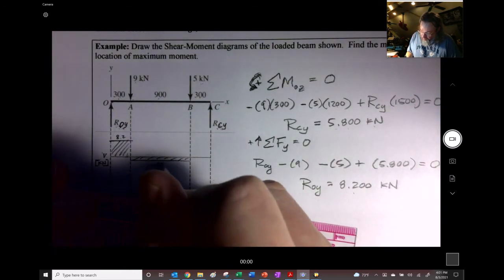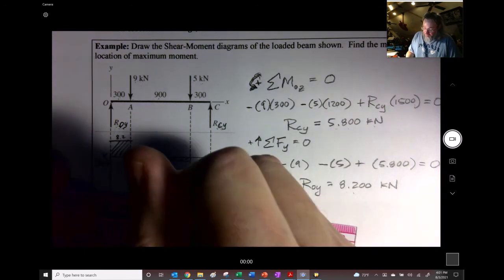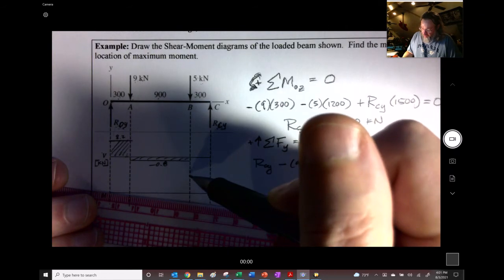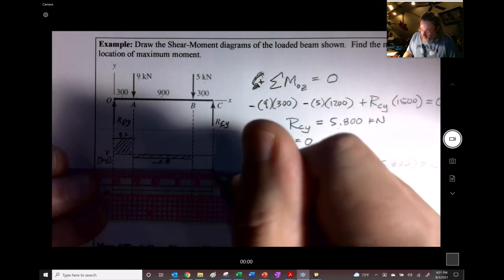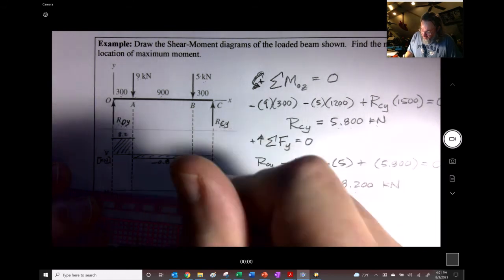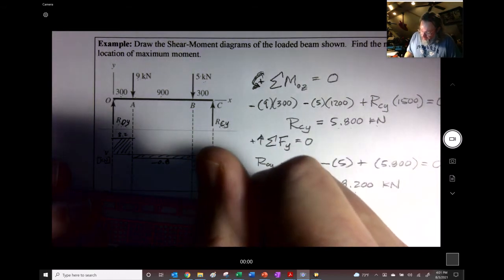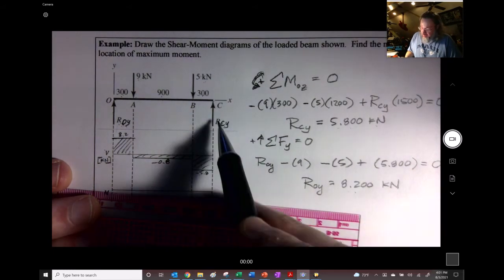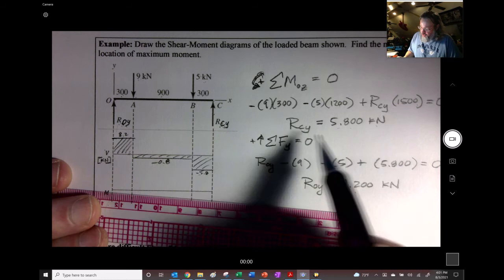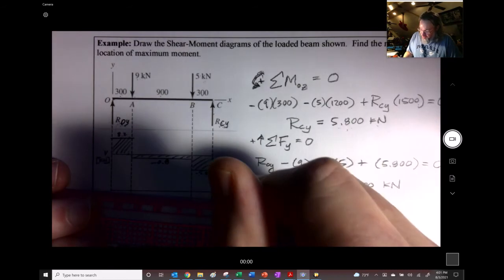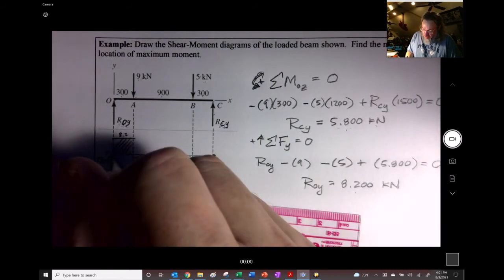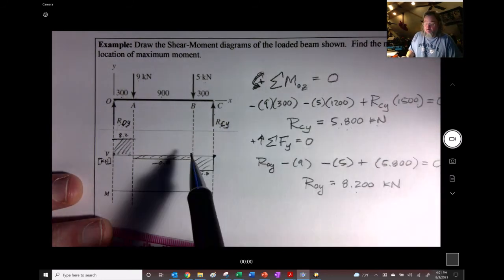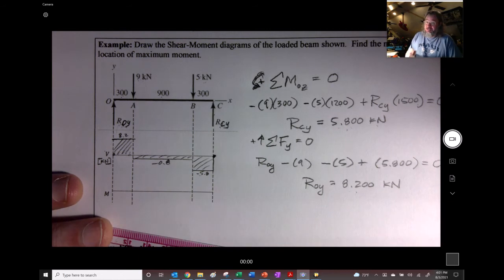So we get a negative 0.8, right? And then we take this 5, and it's coming downwards as well. So that's also negative. So it ends up like being right there. And we get a negative 5.8, right? So that 5 went downwards. It was already negative, so it's a negative 5.8. And then it meets this guy who's equal to 5.8, which brings it back up to 0, right? That's the thing that's like a test for us to see if we did all of this correct right there. If we did that wrong, if it doesn't come back up to 0, you did something wrong.